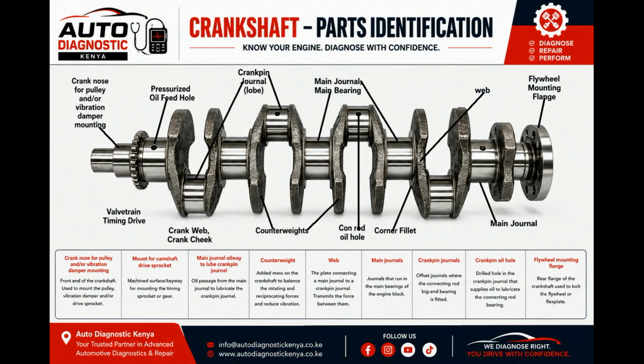The spigot bearing is fitted into the rear of the crankshaft. The front end of the gearbox input shaft sits inside it. Depending on the design, the spigot bearing can be a roller type bearing, or it can be simply a bronze bush. So the rear of the crankshaft has two important jobs: it's connected to the flywheel, and it can support the gearbox input shaft. That's another reason this part of the crankshaft is so important.